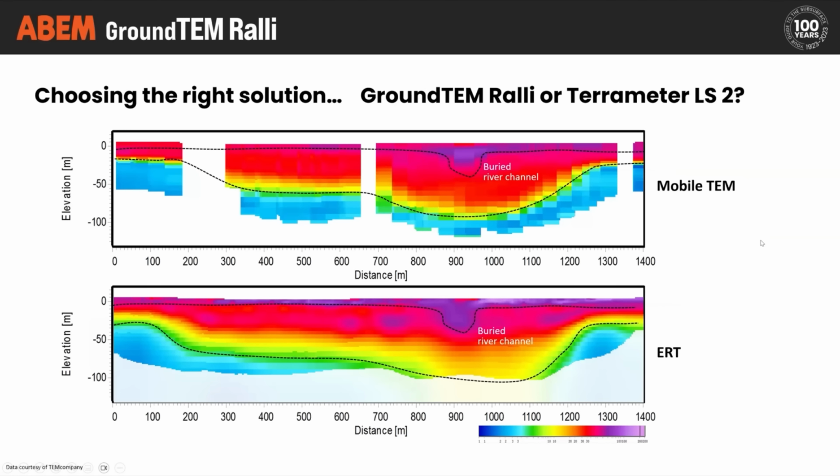Here's another data set doing exactly the same thing, same horizontal, vertical, and resistivity scales being used. And in this instance, we have, again, a very similar overall interpretation of there being some higher resistivity near surface, a concentration of higher resistivity that's been interpreted as a buried river channel, and then a much lower resistivity base unit, which here would be an underlying clay.